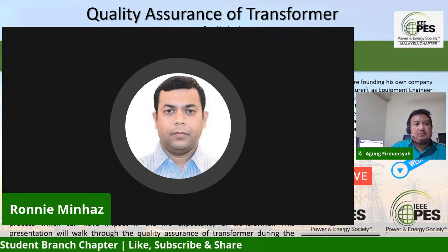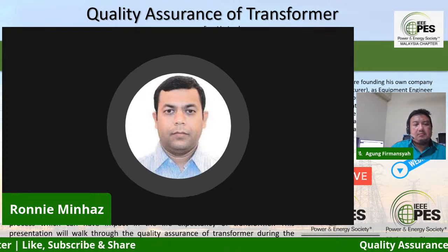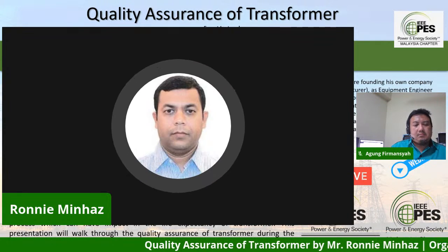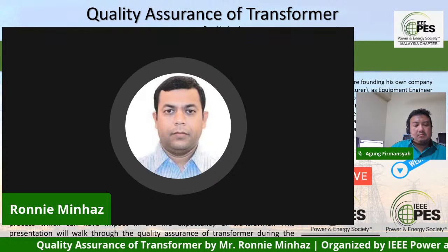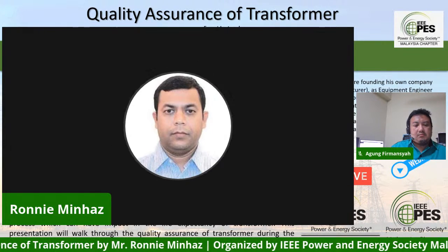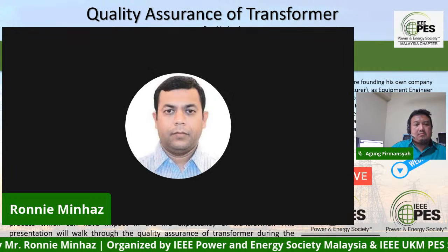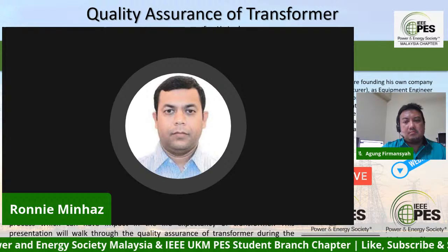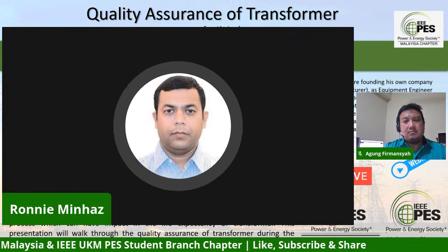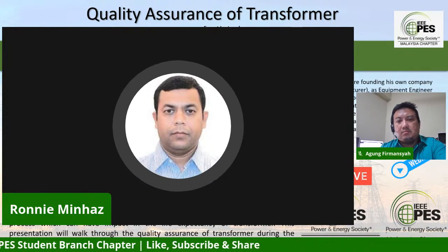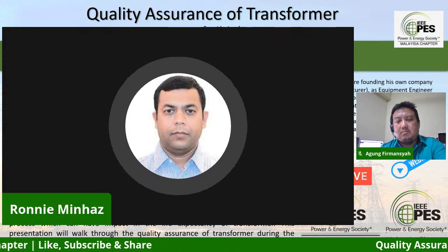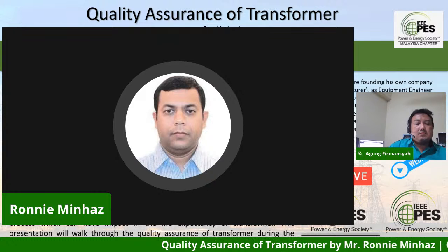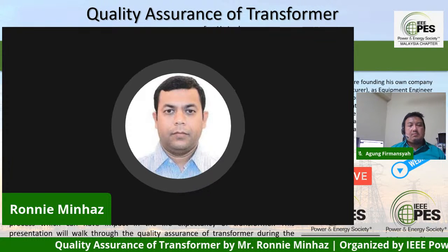So what I did that week, I made a list of how many transformers we have in all our substations. I made a list of every single transformer, which year it was built, who is the manufacturer, which factory in the world it came from. And in this history, let's say a 70 year old transformer, whether in those 70 years we had any problem with this transformer. So I made a list of every single transformer in our fleet.